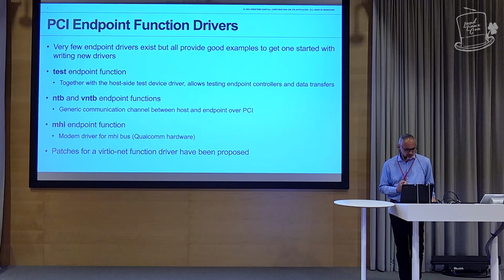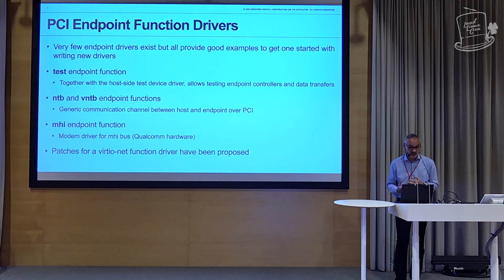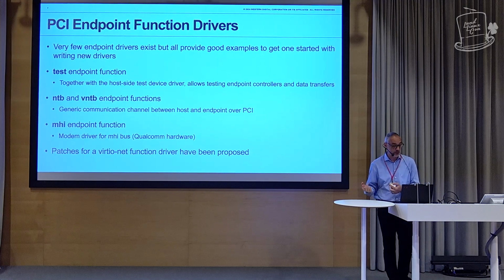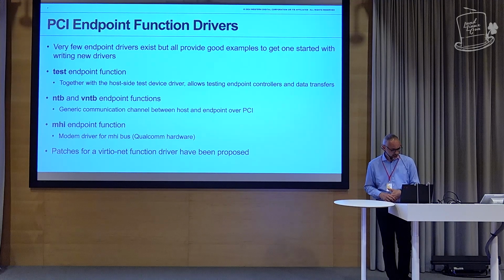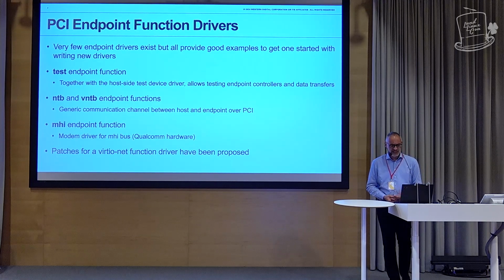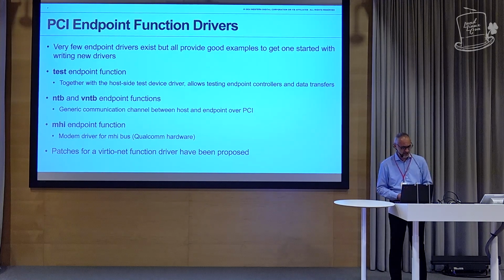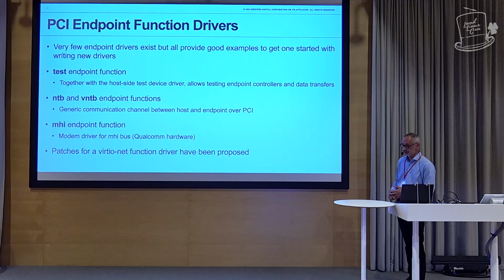There are also the non-transparent bridge endpoint function drivers, which create devices that essentially provide a PCI channel for communicating between a host and an endpoint. So it's just about data transfers. It's not really doing anything in itself with the data. And then there's the MHI endpoint function driver, which is for some Qualcomm hardware MHI bus modem drivers. There are patches being sent or discussion happening also on the list about a VirtIO net function driver that some people want to implement.